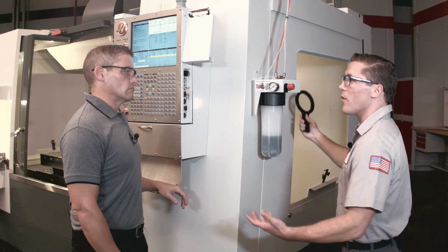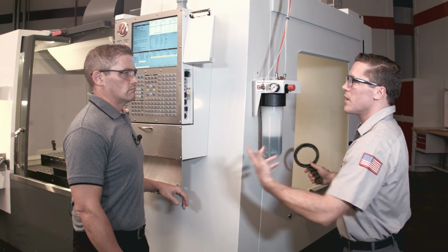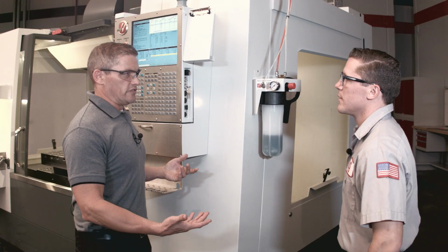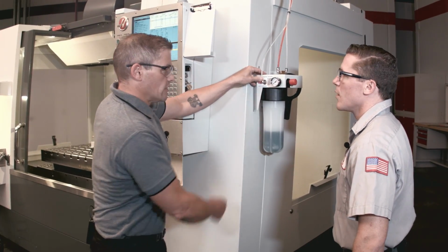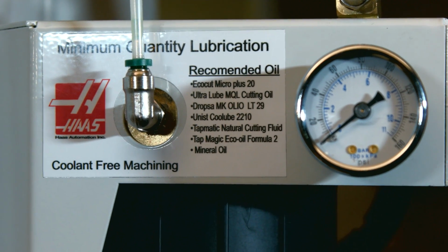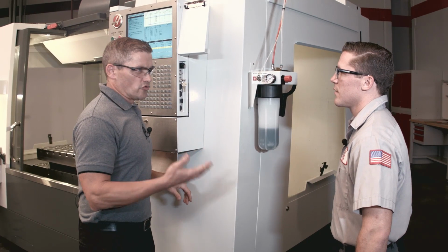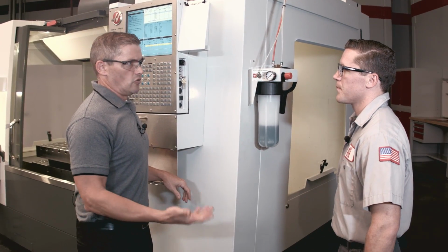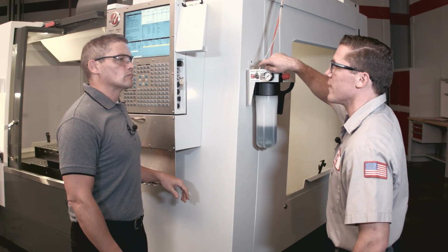And if I need to add more cutting fluid, I simply come over here with this wrench, put it on here, open it up, add my oil, and close it when I'm done. Simple and easy. Yeah, so it also looks like we've got a list of oils that we can reference here. Right. And we're actually using one of the recommended oils that's approved and on this list. That's great. And some people even go so far as to use regular mineral and canola oils, right? Right. So all those that you just mentioned, including what's on the list, those are all safe and non-toxic.